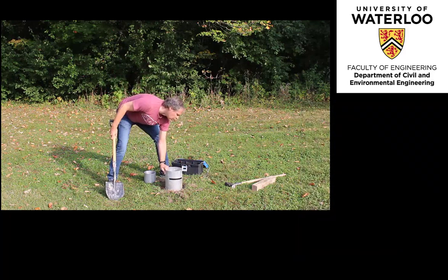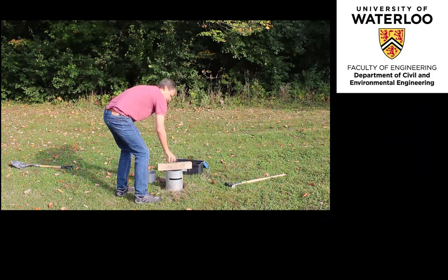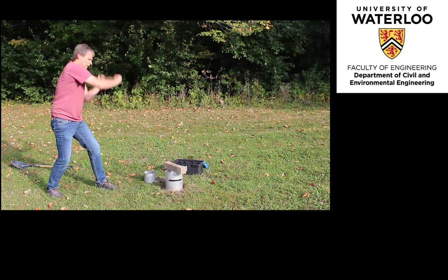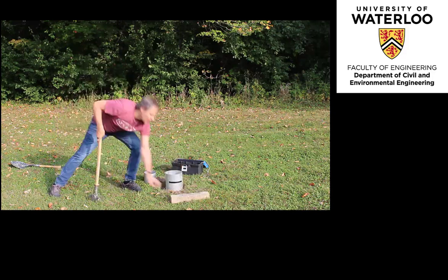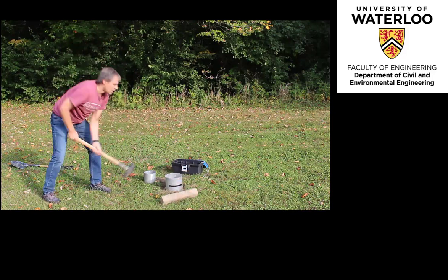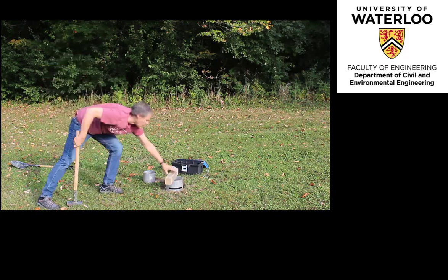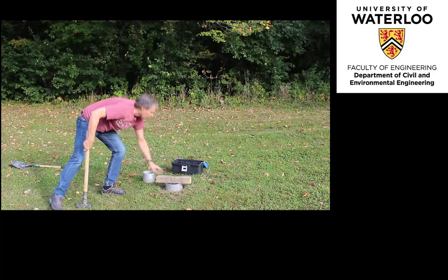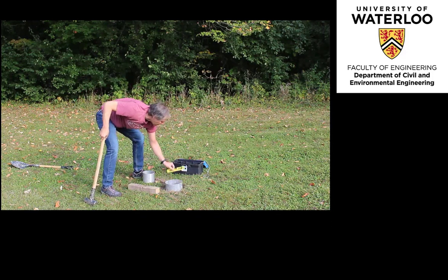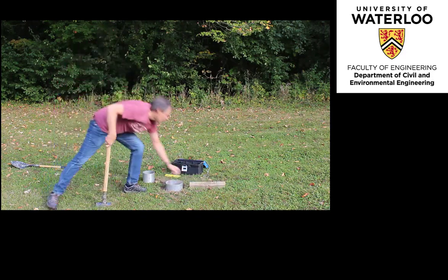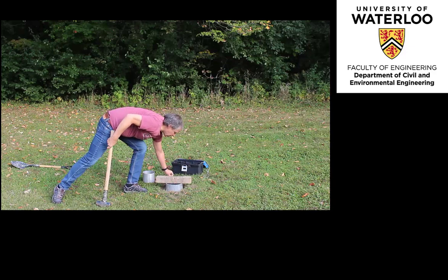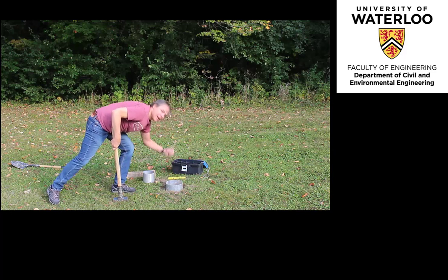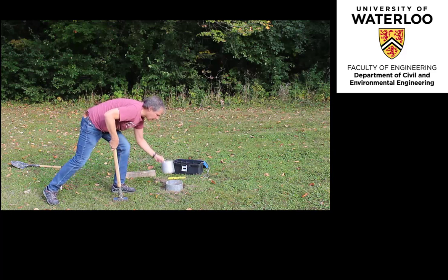Here we have identified on the outer cylinder with a strip of black tape the depth to which the outer cylinder will be advanced into the ground. It is noted that the length of the cylinders can also be changed depending upon the depth of the organic layer and the depth of the test desired. The outer cylinder or ring is first advanced into the soil, followed by the inner cylinder or ring to the same elevation at the top of the outer cylinder, and finally adjusted for level.